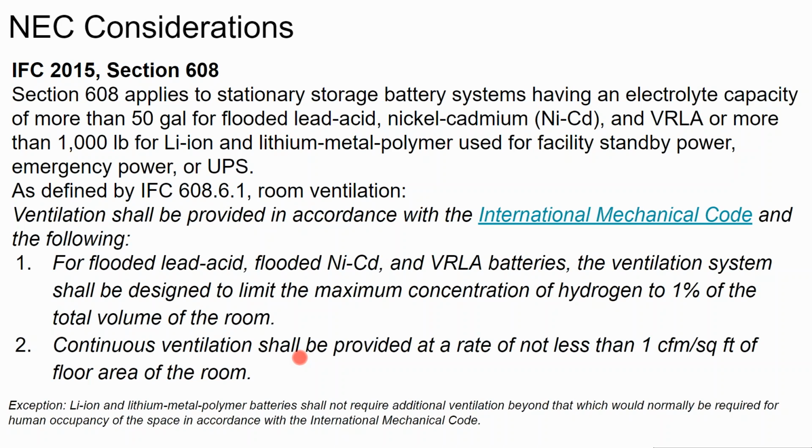And so that has led to the concept of a sealed battery cabinet, where it's just the container that the battery is in that gets continuous ventilation, rather than the whole room that might have a fan clicking on and off like an air handling unit.